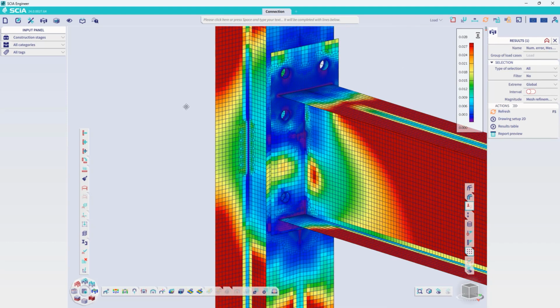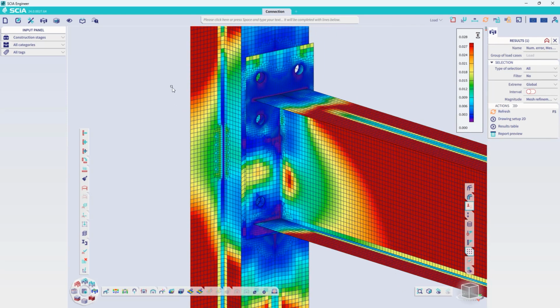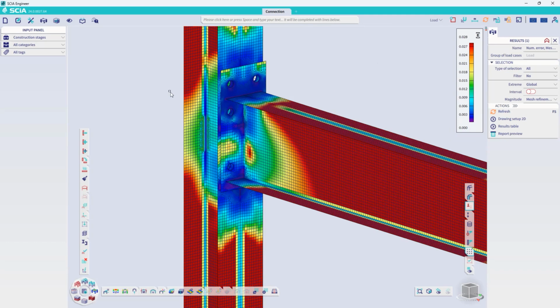And this, as you can imagine, is a tool that can be very useful for the user that does this kind of modelization, mostly in metal, of mechanical details, because it can improve the accuracy of the results without really any effort on the side of the user, because the user just needs to select the target error and apply the loads, and after that, the software itself will compute the optimized mesh and will use it for the linear and nonlinear calculation that will be done.